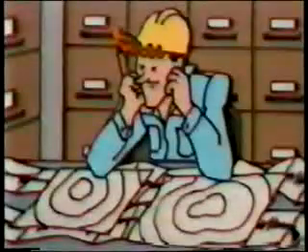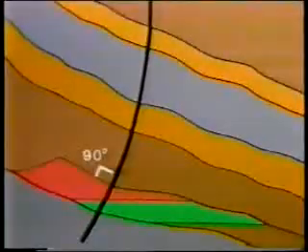We must not assume that all of this data came from vertical holes. Obviously, there are situations where it's impossible or not feasible to drill a vertical hole, as when the subsurface reservoir is beneath a lake, river, or in a metropolitan area. In such cases, the drilling rig is set at a more convenient location, and the hole is deviated to reach the reservoir. In the early days of drilling, many wells were quite unintentionally deflected, what we call a crooked hole. Crooked holes are still a concern in regions of structural deformation and steep dips, where a vertical hole tends to deviate in a direction perpendicular to bedding.